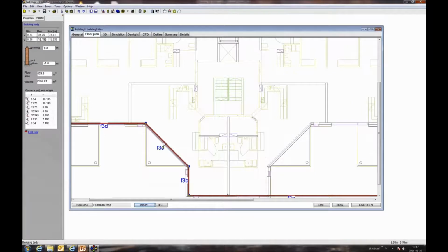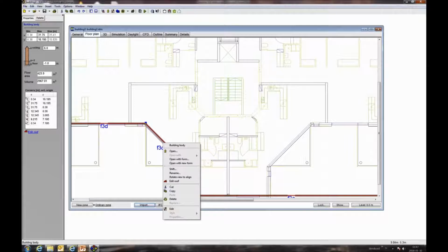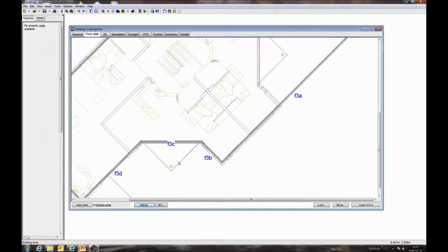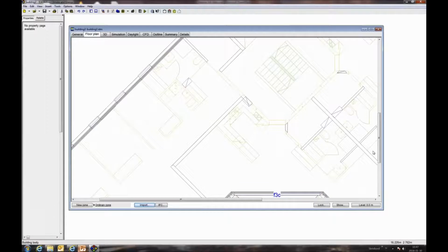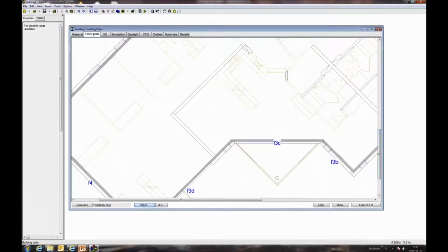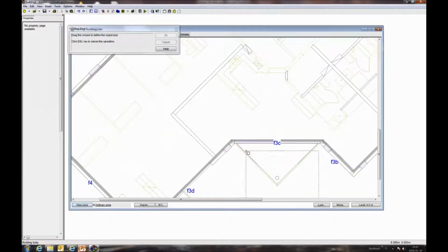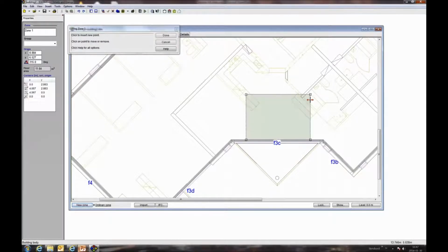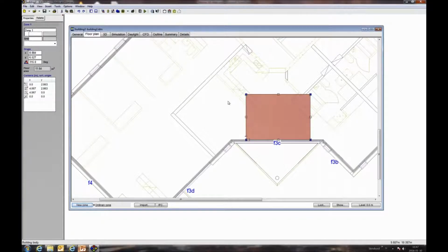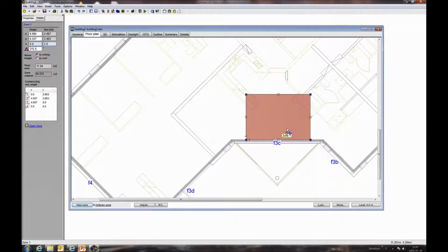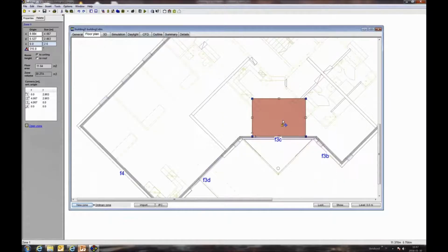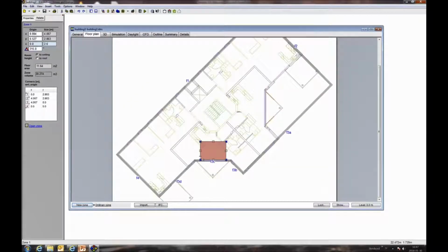And another nice feature is the rotate view to align. So I select an edge, I click rotate view to align, and then it's very easy to add zones aligned with this. So now I can create these shoebox rooms that we need for the climate zone model quite easily in the correct place.